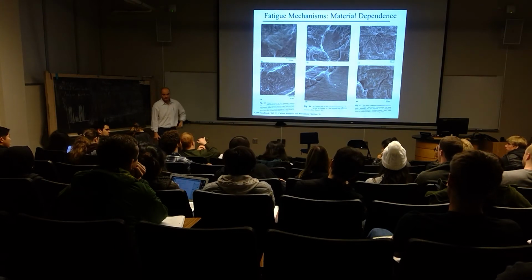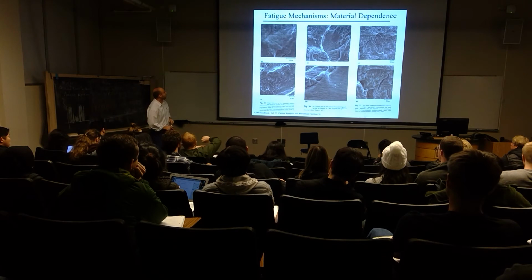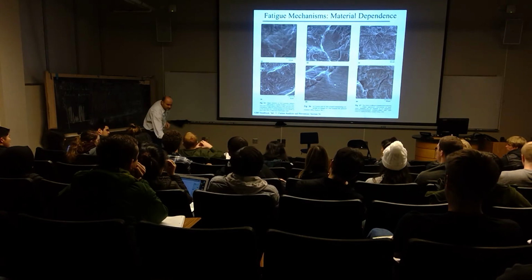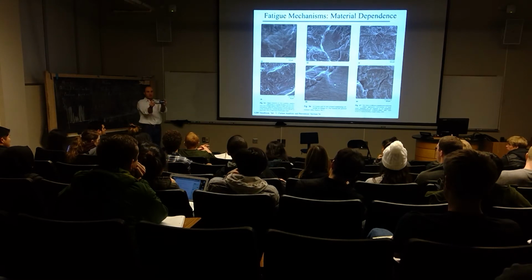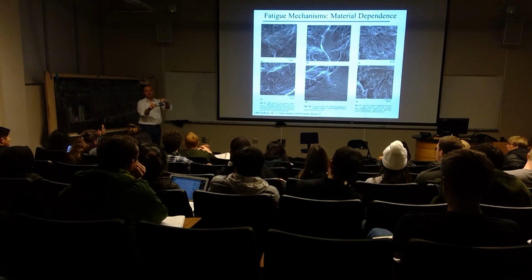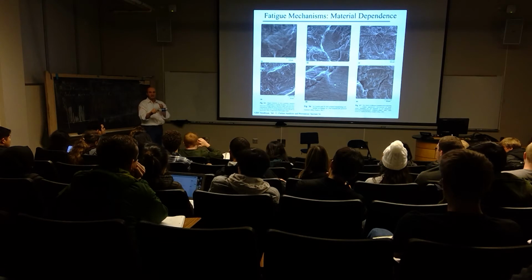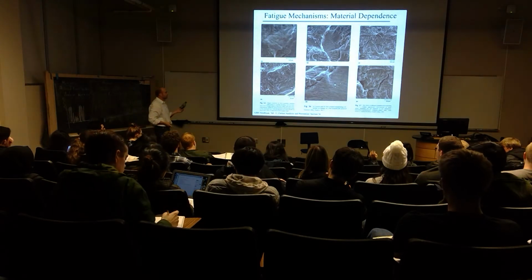When you see rotational bending in this context, is that taking a shaft and torquing it? That's a situation where you have a shaft and it's subjected to a bending load. The bending load doesn't change orientation, but the shaft is rotating. So all of the surface is subjected to the same magnitude of maximum tension and maximum compression. Because on one cycle, because of the bending moment, it goes from maximum tension to maximum compression. Okay. So that's exactly what this is.